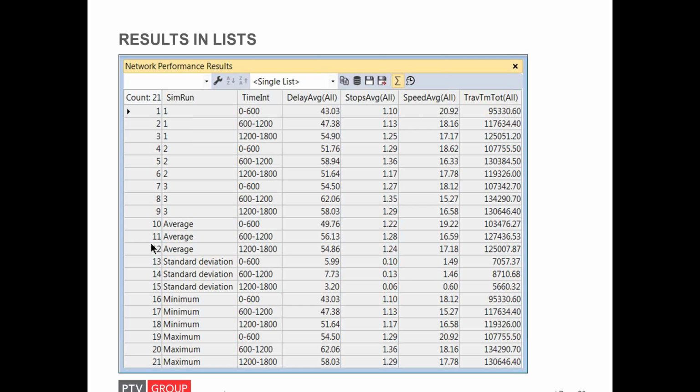And performing multiple simulation runs for one scenario is what you typically have to do because microscopic simulation in Vissim is stochastic and not deterministic. Many decisions and properties of vehicle driver units in Vissim are drawn from distributions rather than just using a deterministic variable. And this is done to reflect stochasticity observed in the real world. For example, there's normally not one single driver entering the system at the exact same time with the exact same desired speed every day. And the consequence for the modeler is that he has to conduct multiple simulation runs per scenario to account for this stochasticity.